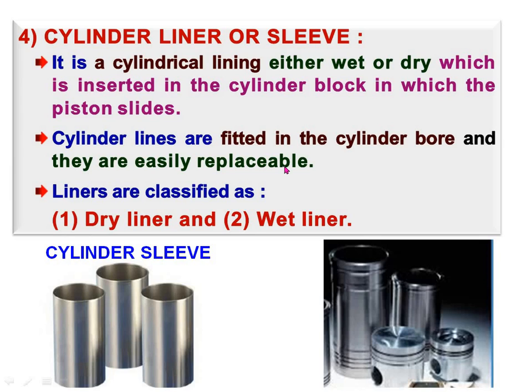As I have told, in each and every cylinder bore we have to insert a cylinder liner separately, and these are easily replaceable. So during working, if it gets some damage, then it may be easily removed and a new lining or new sleeve may be inserted at less cost.